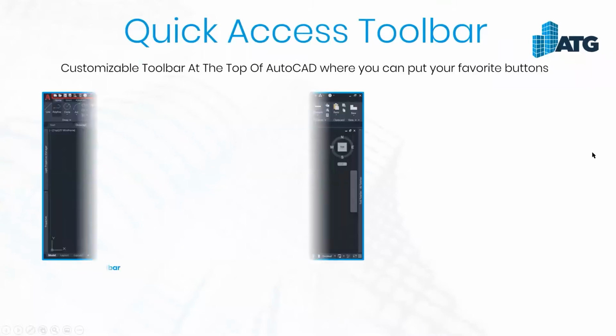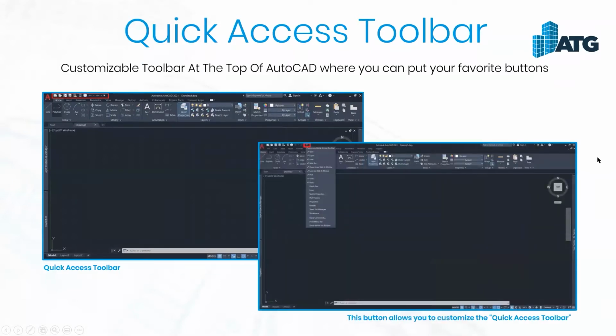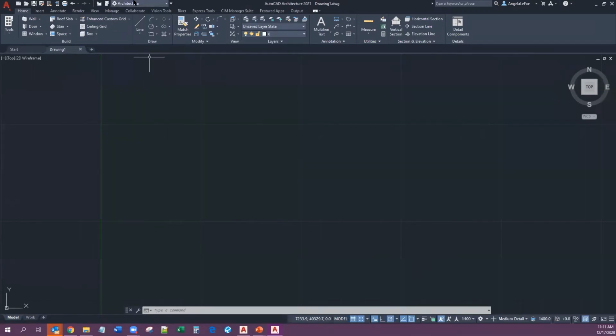The quick access toolbar, it's customizable. It's at the top of your AutoCAD interface, and you can put your favorite buttons up there. And this just shows in the red box, you can see the quick access toolbar, and you can see how to customize it. So hopping back over here, this is the quick access toolbar, and you'll see this down button up here. This lets you customize it. And you'll see the familiar check marks. And if you see what you want up here, just check it, and you'll notice it shows up at the top there.